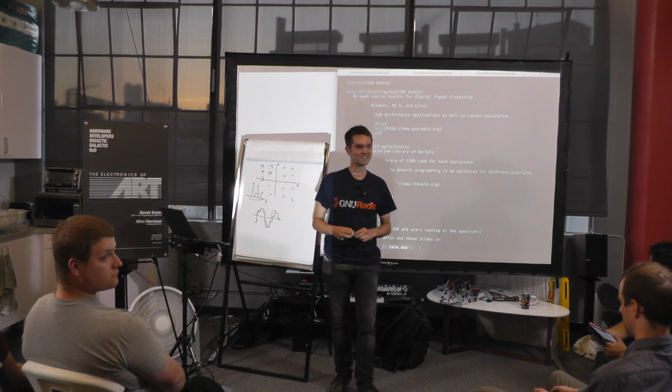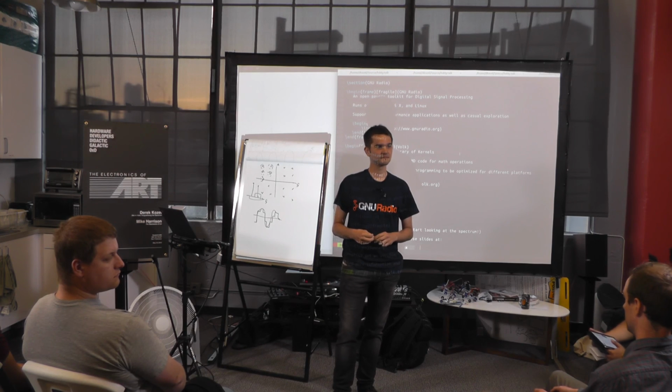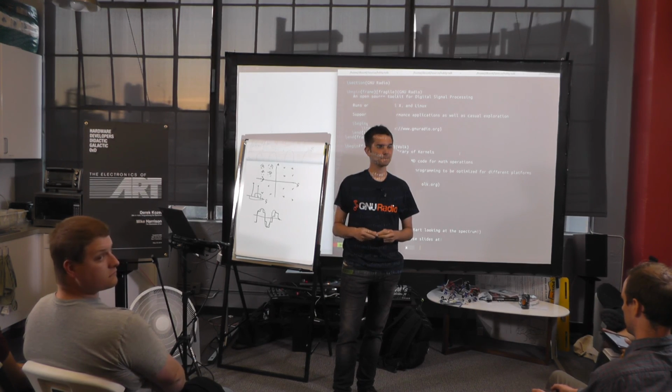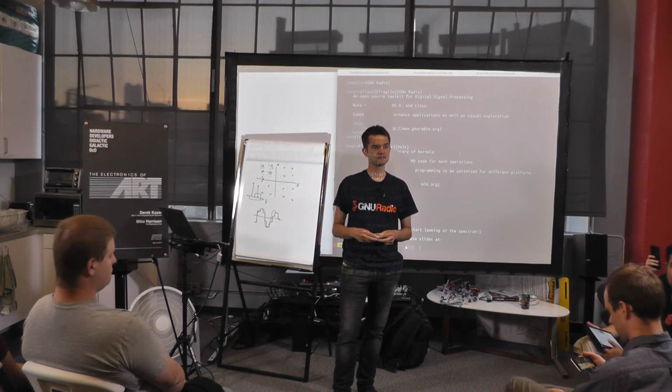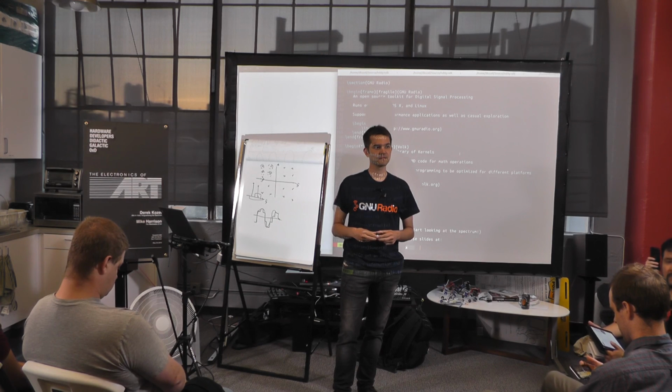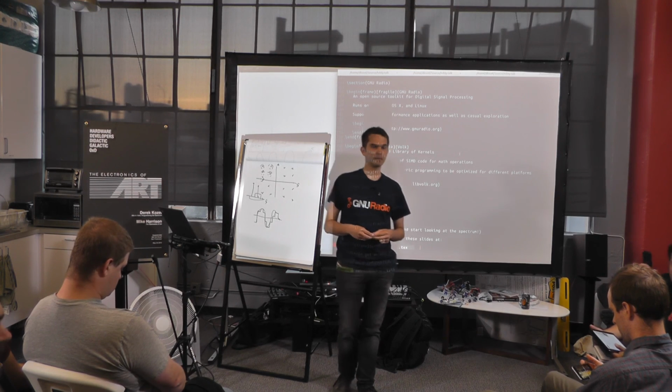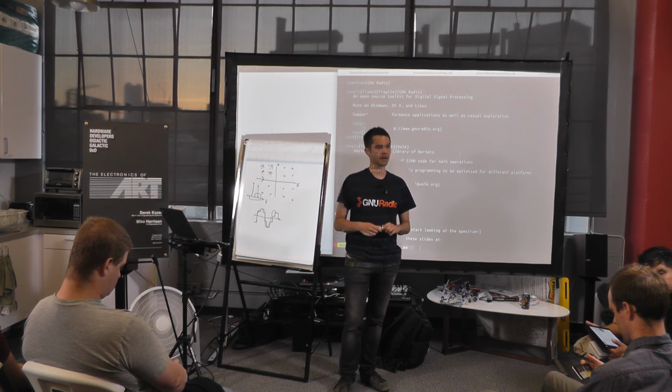When you were talking through the spectrogram, you mentioned that these signals weren't demodulated yet at that point. But I'm confused because you've only got 50 megasamples of bandwidth in the radio. So is there a stage of demodulation that's happening before that? So what's happening is there's down mixing happening.